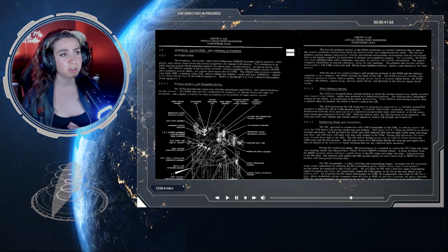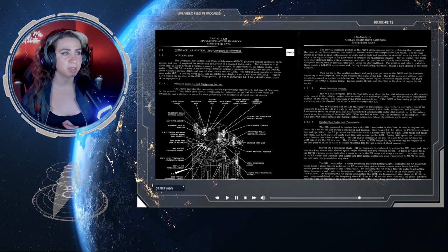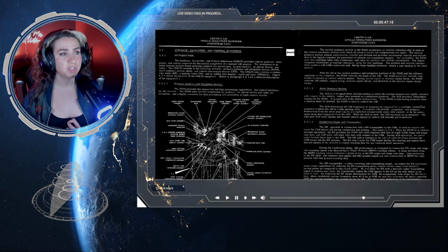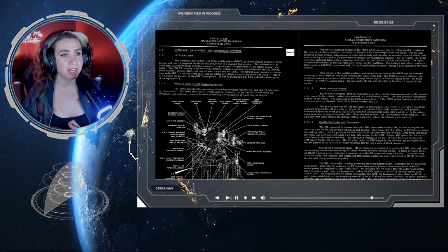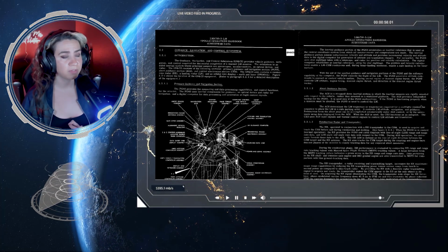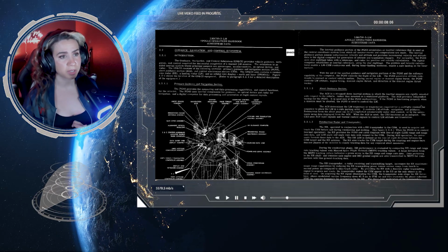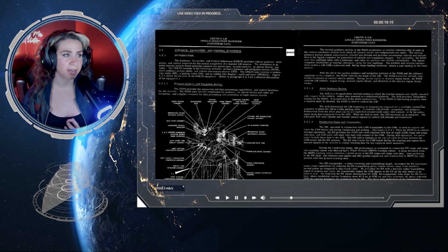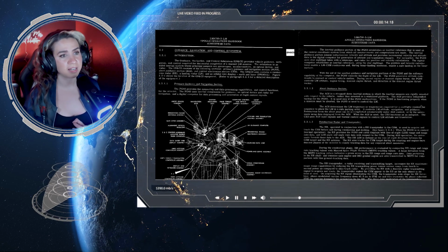With the aid of the inertial guidance and navigation portions of the PGNS and software capability of the computer, the PGNS controls the flight of the LM. The PGNS generates attitude commands to correct or control vehicle motion. During ascent engine or descent engine burns, the PGNS controls LM attitude, engine firing, descent engine thrust, and direction of the descent engine thrust vector.